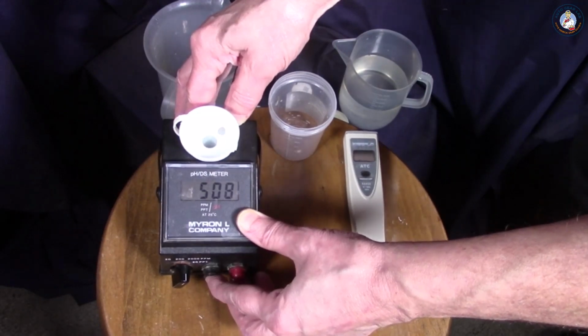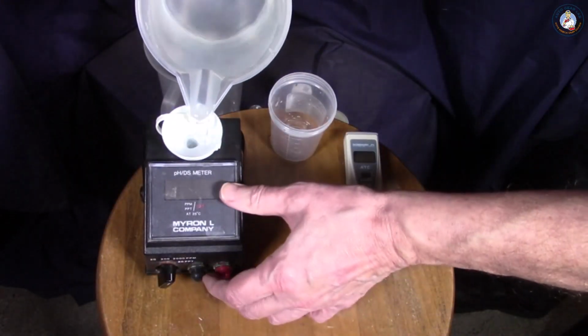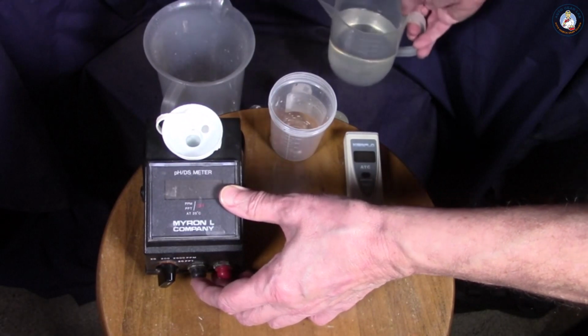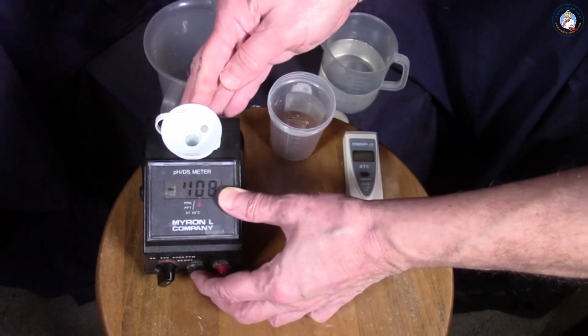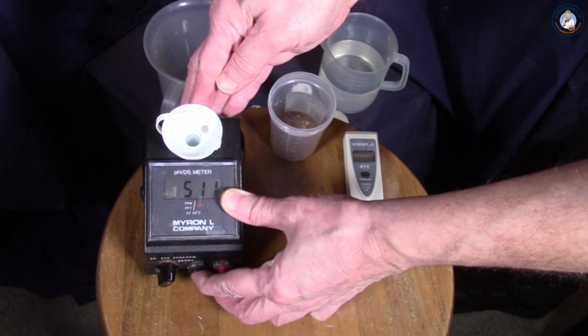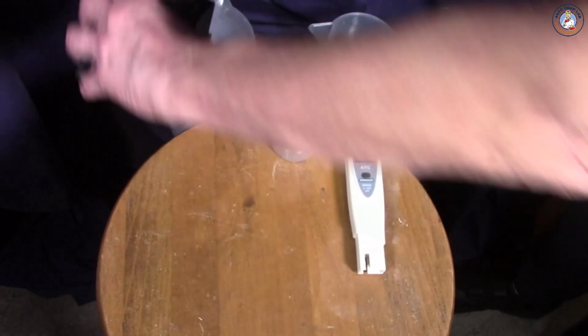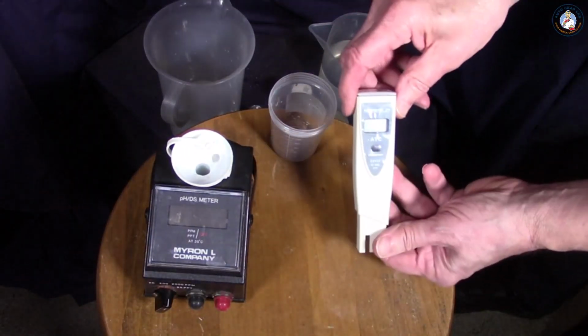Now this TDS is in parts per million. Parts per million is a calculation based upon micromhos or microsiemens. The meter actually reads the resistance of water passing across two probes, then calculates the TDS. And you can see the repeatability is about 511, which is maybe 2 parts per million higher. So it has a good repeatability.